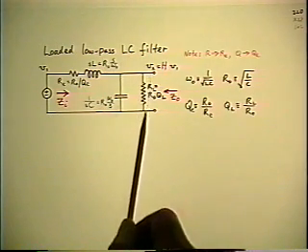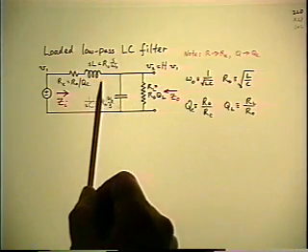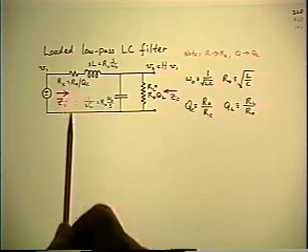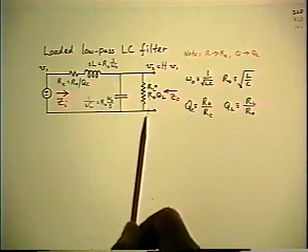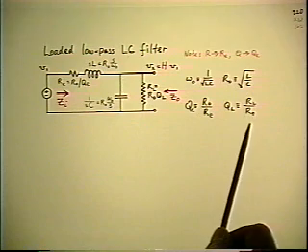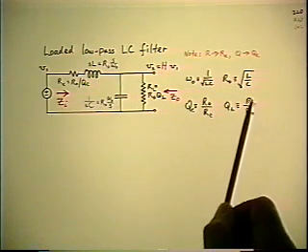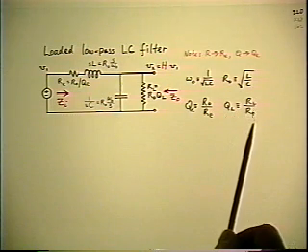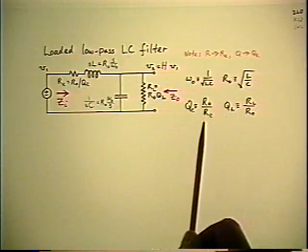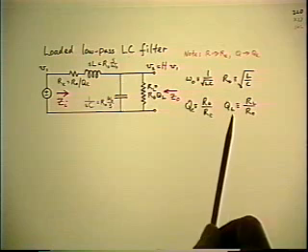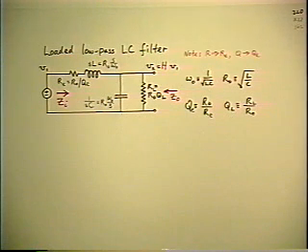But in the case of the load resistance, it's in parallel relative to the tank instead of in series. So you get 0 losses when RL goes to infinity, and that gets you back to the previous case. So that's the reason for defining the QL upside down compared to the QE. Both Q's go to infinity in the appropriate limiting cases of 0 damping.